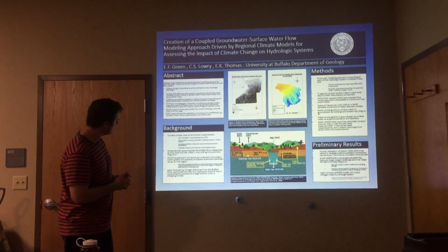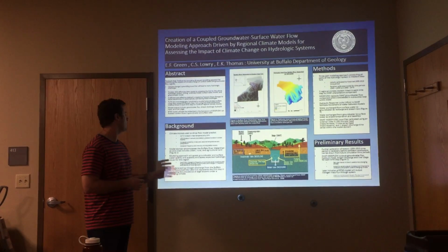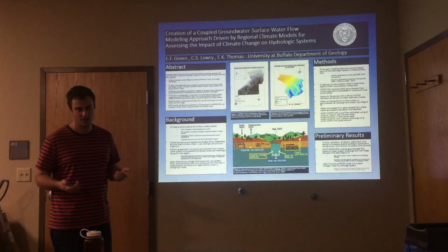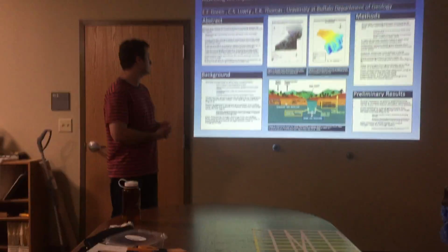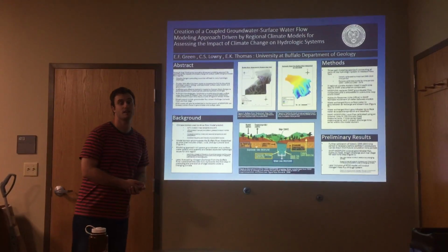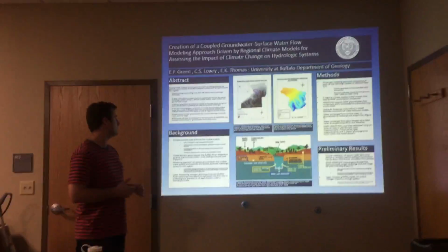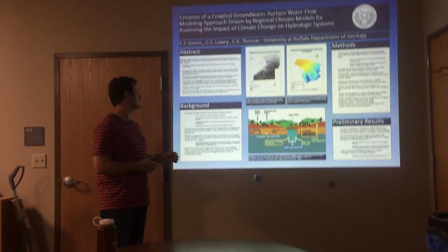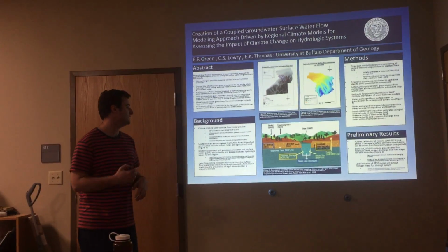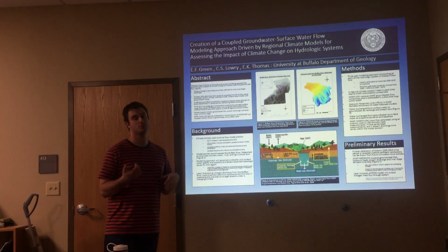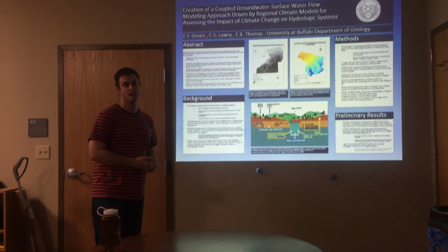And that way we can forecast nutrient fluxes, specifically nitrogen fluxes, in groundwater and surface water in relation to climate change. So the climate models that we're using predict a 3.6 degrees Celsius increase in mean temperature by 2070, the end of our modeling time period. Over that corresponding time period, we see a 15% increase in annual precipitation, with a greater increase in winter months relative to the other months. We see an increased variability in daily and seasonal temperatures and precipitation. And finally, and perhaps most importantly, for my model, we see an increased frequency and intensity of precipitation events moving into the future.